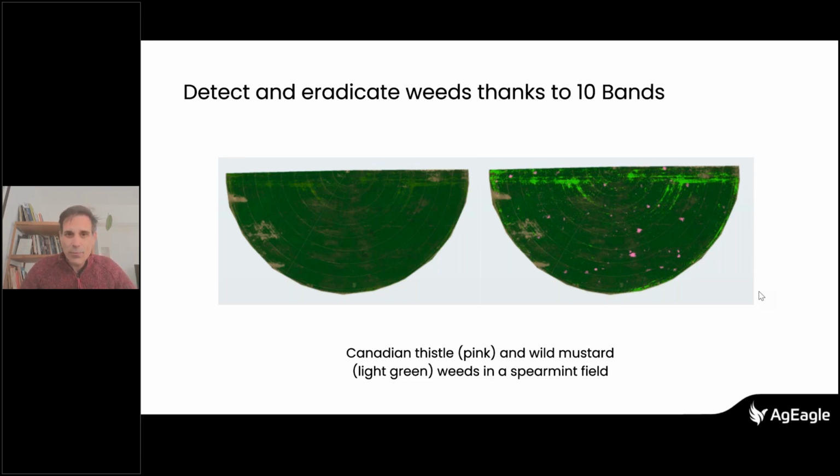And this is so important, why we pay so much attention to the calibration panel when you fly, the DLS, everything you can do to have good reflectance data is needed if you are going to make a time series. If you want to compare one image to the other, the values of the reflectance need to be comparable.